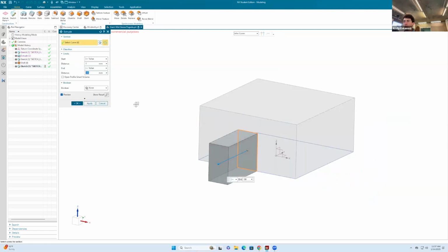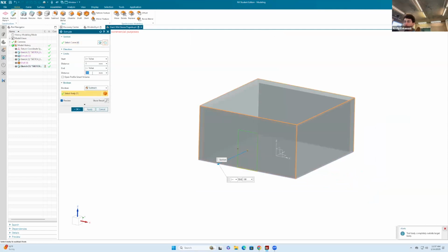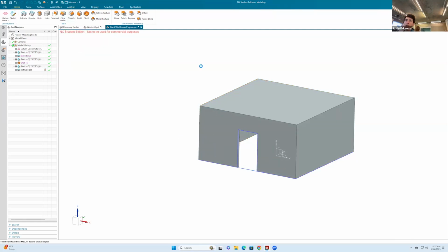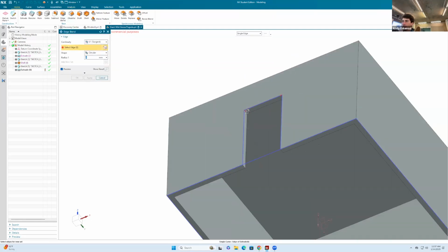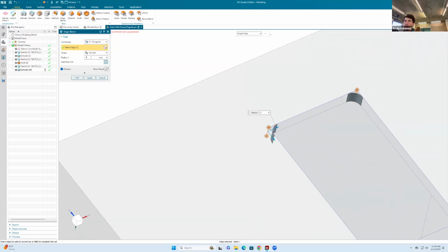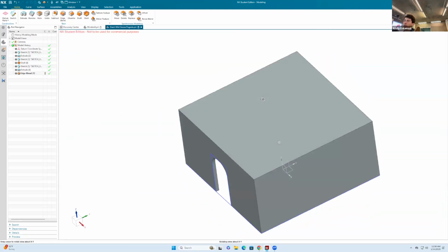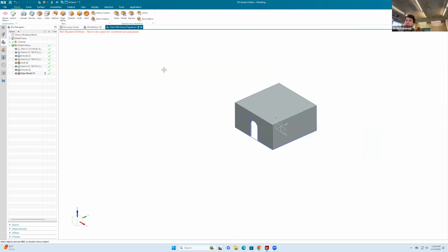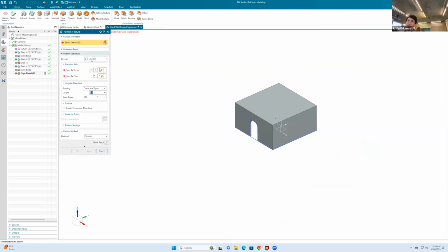Then I'm going to extrude cut, subtract, -5. And now we're gonna edge blend this in here, that in there, and let's blend it by 10. I'll say, okay, good. So now, as you can probably guess, I'm gonna go here to our friend pattern, and I'll make a circular pattern.